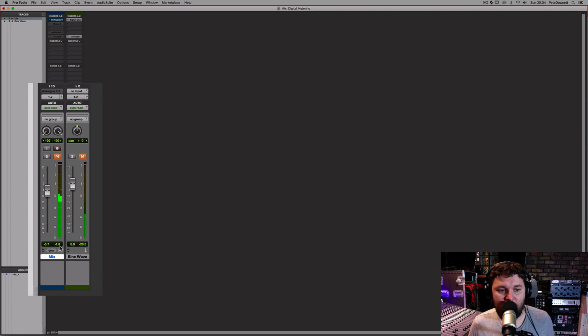If we look down at the bottom here, we've got 2 other numerical readings. This first one on the left is showing you the level of the fader, so this is at minus 5.7, but the one on the right is showing you the maximum peak level during the portion you just played. And if I left click on this, it will reset. That's great. So this is showing you the dBFS reading. It's showing you the instantaneous peak levels.